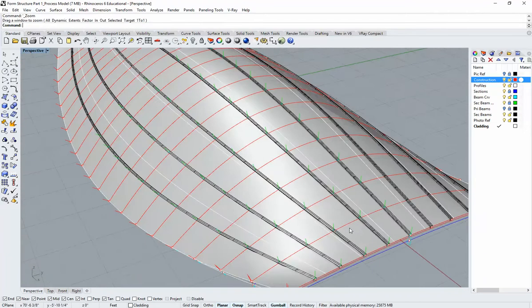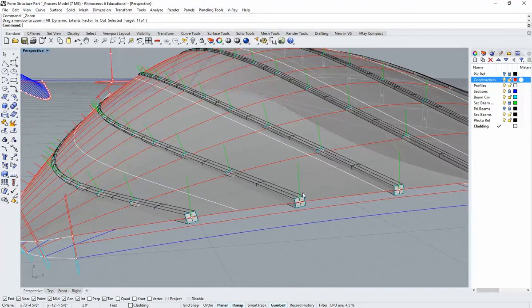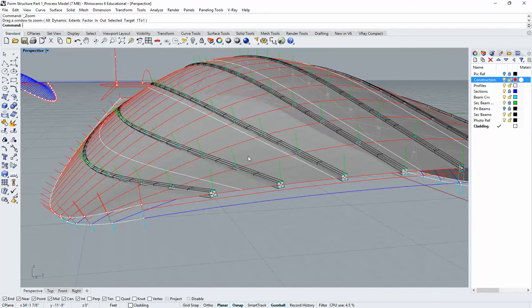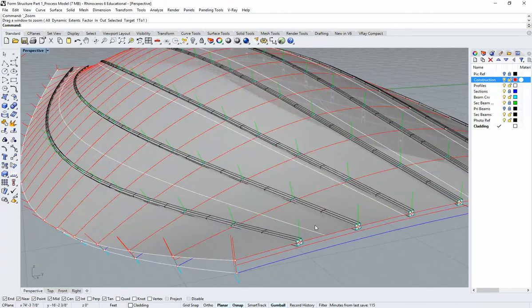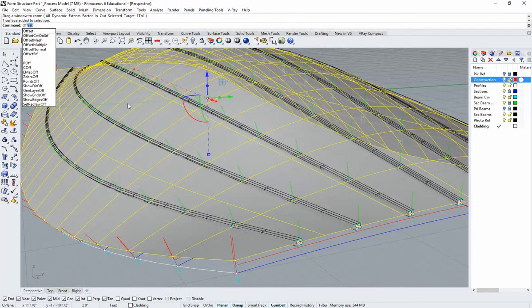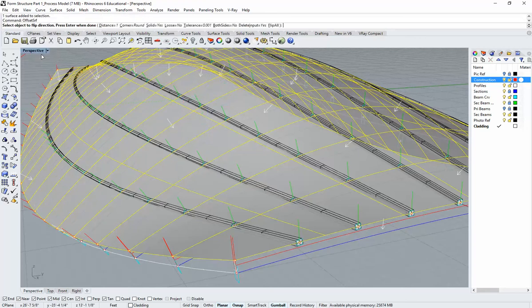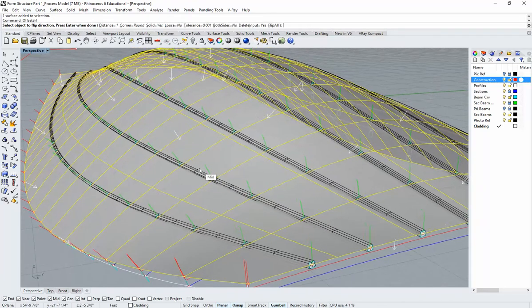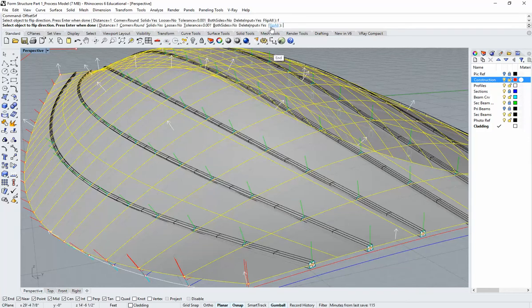And then I'm going to find the offset, because of course this intersects the other structure, and that's not high enough. So what I'm going to do to find the offset for those curved beams is to simply offset the surface. So I'm going to type in offset surface. And my screen is showing the direction of the surface to have a downward direction, so I'm going to type in F and flip that. Okay, which is the same as clicking this button up top here, flip.